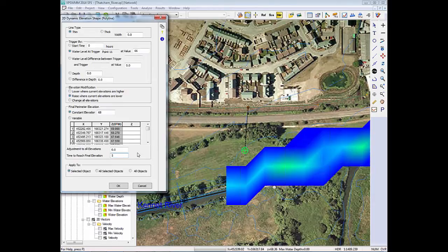And we know that the mobilization time of a fire brigade with the sandbags is 5 hours from the point we call them till the point the 2-meter wall will be up. Right? So we can put all these parameters in here, press OK, run the model, and see how this type of mitigation helps or doesn't help.